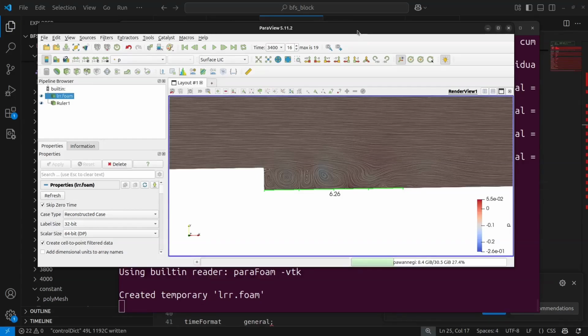Now, whenever you are given a task to run a simulation using the Reynolds average equations, then you will know which model you should prefer based upon whether the flow is in the free shear, whether there are swirls or not, whether there is reattachment of the flow or there is a separation bubble which you have to take care of. Then depending upon that you can take a call. In industries, in real life, whenever you are simulating something, always try to solve it using the k-epsilon model and see what you are unable to capture depending upon the simulation results and the theoretical expectations. Then use a more complicated model.